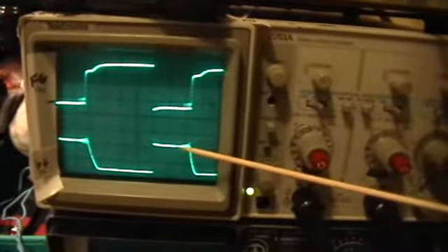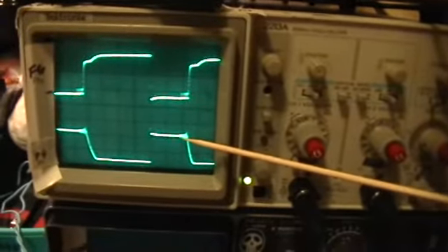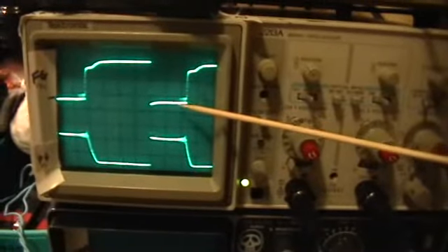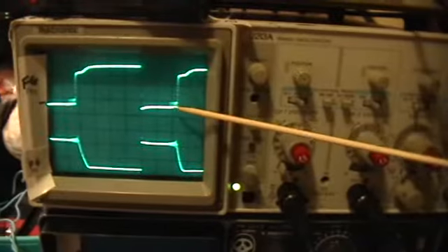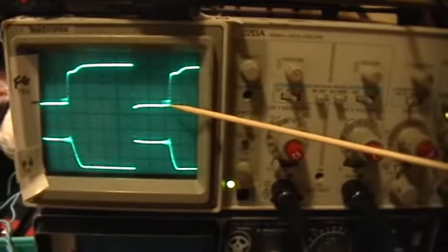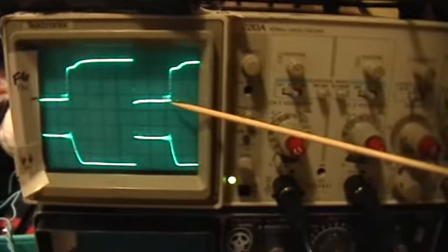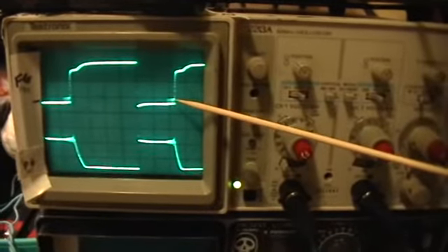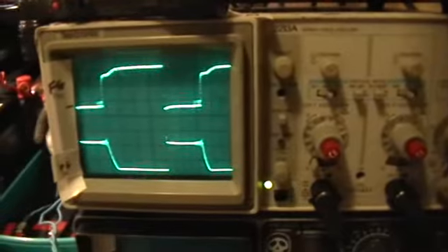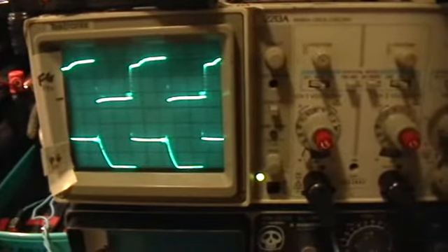Okay, so you see this parasitic oscillation right there that I showed in the last video, and you see it also on the signal coming as the 555 timer turns off. You can also see the little signal there too. Okay, and as I turn the duty cycle of the control of the timer, you can see that, let's see, we should be actually triggering on trace 2.